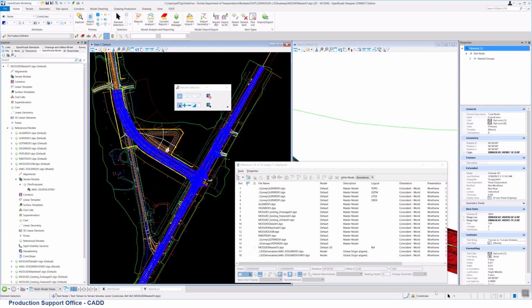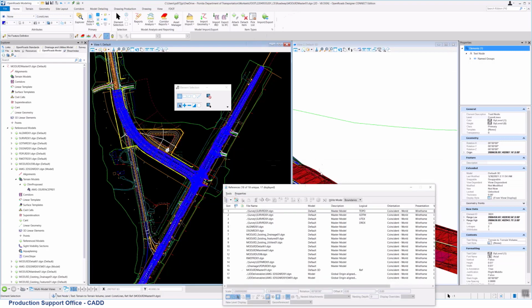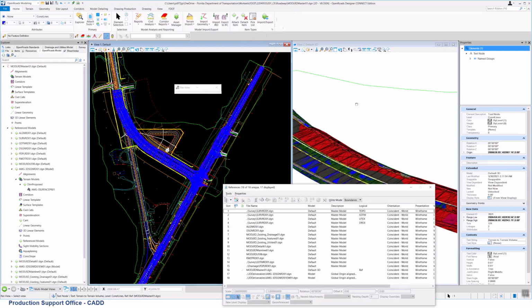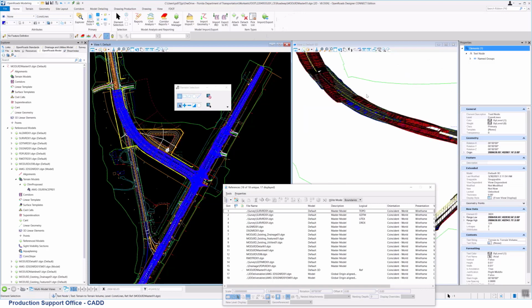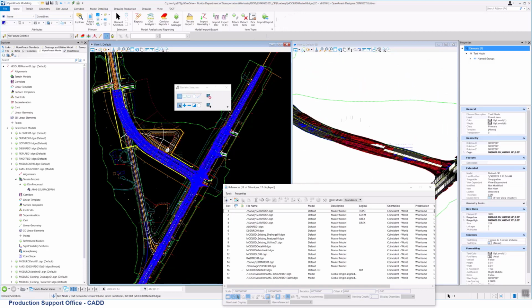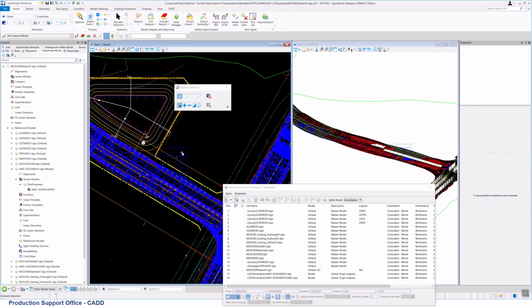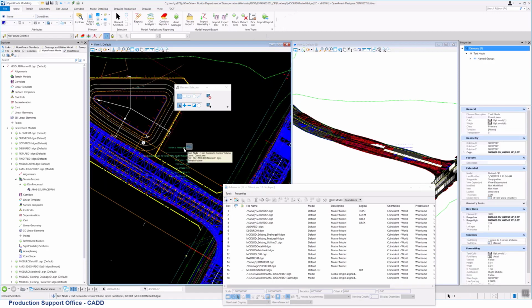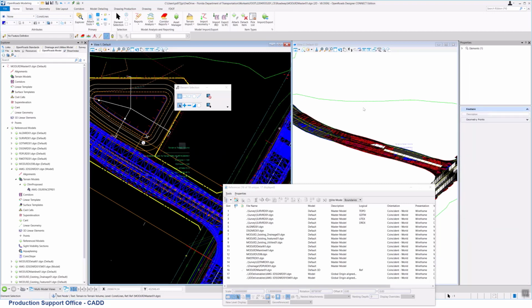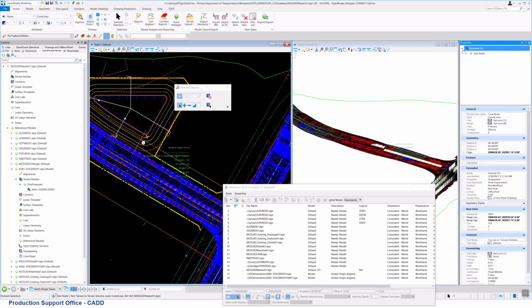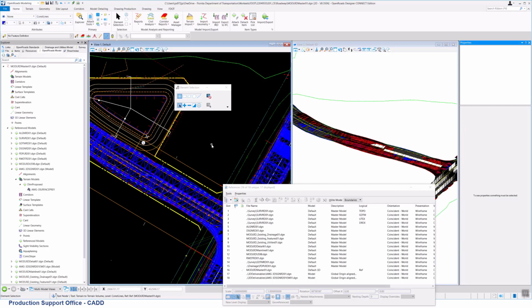Alright, we're going to move on down to chapter 7. Just flowing straight in there. We have the master model already open. One of the things that comes up often is, how do you clip the existing terrain? If you're trying to do a visualization, it can be challenging. First of all, I'm going to delete this thing that I just added because it's in the way. If I right click here in properties, I should be able to delete it. There we go.